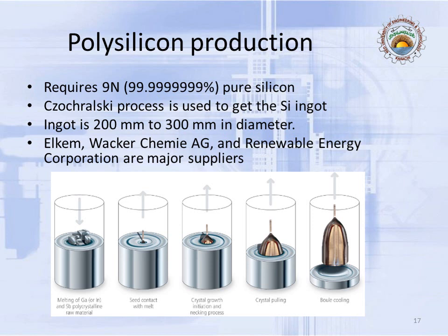So it depends upon the foundry as to what is the maximum size of a wafer that a foundry can process. The bigger the size of the wafer, the smaller the wastage in producing the ICs, and therefore it will be more profitable. But again, to have accuracy over an area as large as 200 or 300 millimeters is fairly difficult. These are the companies that usually produce these silicon ingots, and these are basically European-based companies mostly.